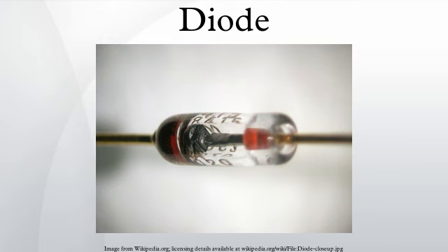Other common numbering/coding systems include GD series germanium diode. This is a very old coding system. OA series germanium diode, a coding sequence developed by Mullard, a UK company. As well as these common codes, many manufacturers or organizations have their own systems too. For example, HP diode 1901-0044 equals JEDEC 1N4148, UK military diode CV448 equals Mullard type OA81 equals GEC type GEX23.